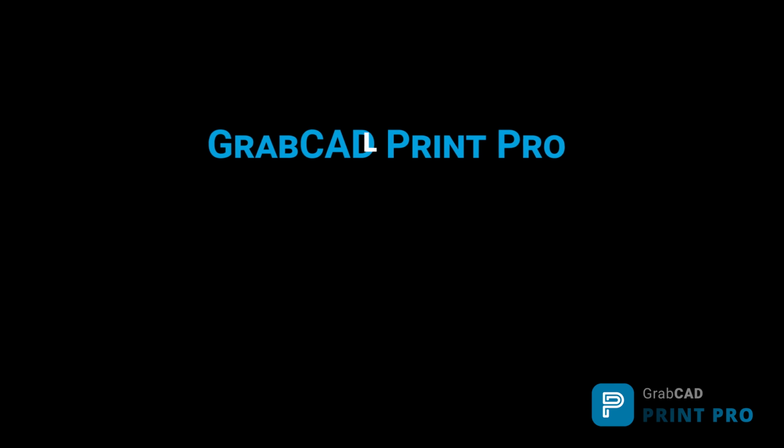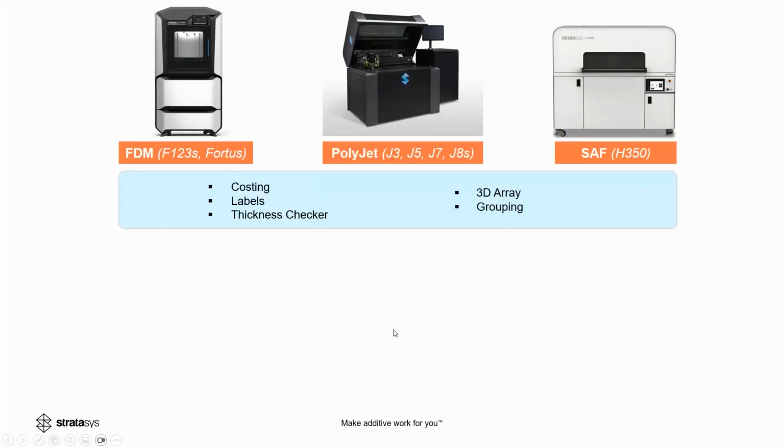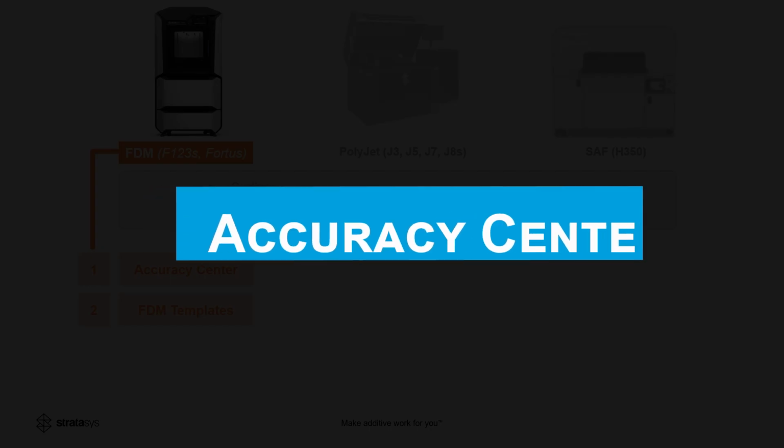Now let's talk about FDM-specific features in GrabCAD Print Pro. We just covered how FDM, PolyJet, and SAF have costing, labels, thickness checker, 3D array, and grouping in Print Pro. But let's talk about FDM-specific features. Accuracy Center allows you to laser scan your part and correct for warpage on the second print. And FDM Templates let you lock down your settings for FDM so that everyone uses the same settings. As of recording, these features are only available for FDM type printers, but in the future, they should be available for all Stratasys technologies. So let's talk about Accuracy Center.